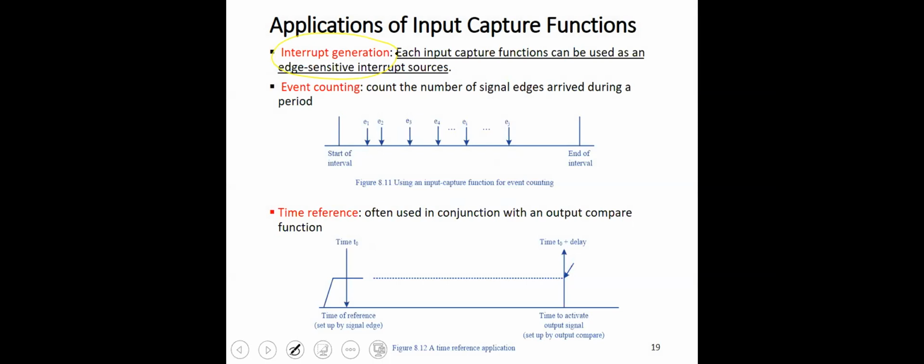let's assume that you want to connect 8 switches to the microcontroller, and whenever any of these switches is pressed, you want to interrupt the microcontroller. This can be achieved using port T by enabling the input capture functionality. Without this, you have only the IRQ pin and the XIRQ pin to monitor external events.